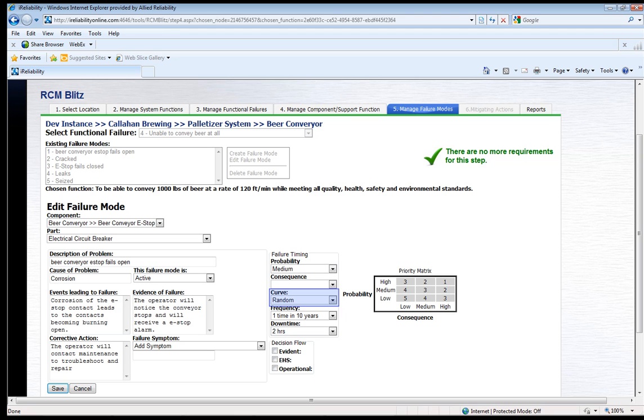D. Best new. These items have a very low conditional probability of failure when first put into service. This quickly increases to a low level of random failures over time. Most hydraulic and pneumatic components fit failure pattern D. E. Random failure modes include human-related errors, as well as ball bearings that have been installed and maintained using precision maintenance techniques. F. Infant mortality. These failure modes include low voltage electrical components and parts as well as human errors that occur at the time of installation, not using precision alignment when installing rotating equipment, for example.